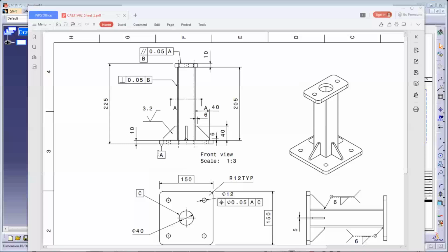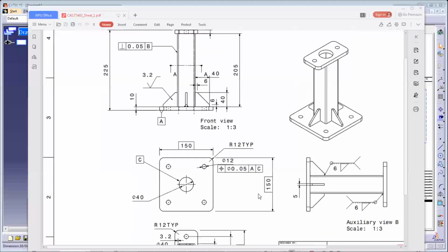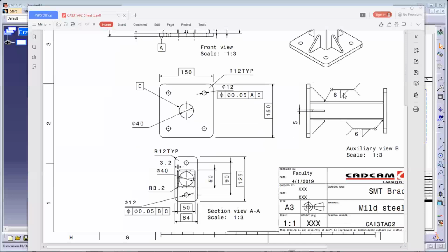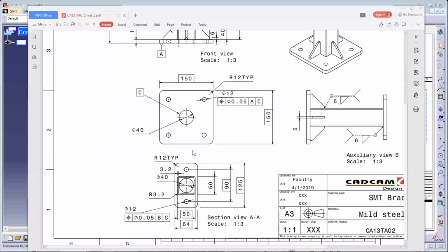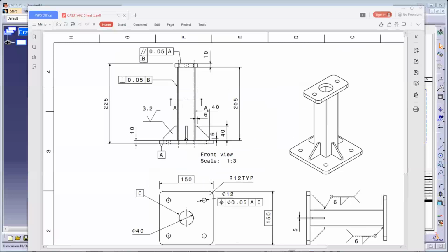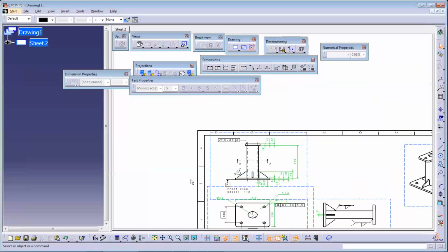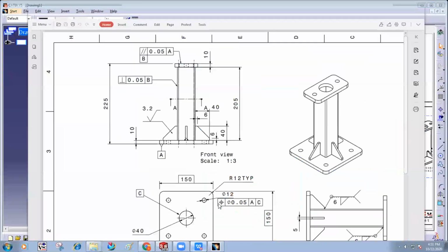So what symbols are we seeing? Data identifier, ABC like that, then GD&T feature control frame, and then this position tolerance symbol, and box sizes or basic sizes, how we can define. After that, welding symbols. One more thing is how to put the B datum over here. Parallelism I think we have already defined. So how to put the B? I think B is not defined here. So B is B here.